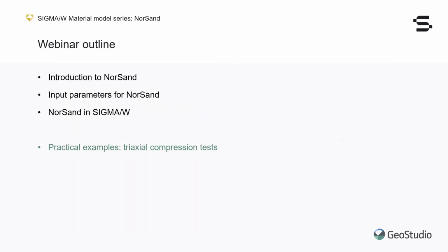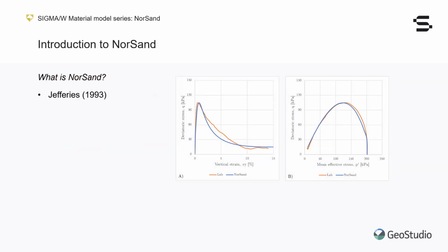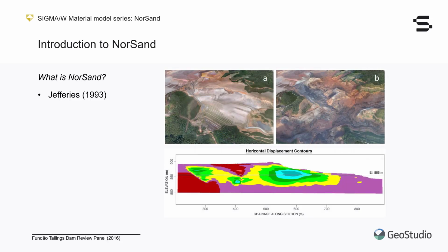Let us start this webinar by reviewing the important basics of NorSand. NorSand is a constitutive model created by Mike Jeffries in 1993, which has been updated and upgraded considerably through the years. It is a soil model specifically designed to correctly simulate sand behavior for a variety of states, from dense and dilatant samples to loose and very contractive ones, such as what we see here, where static liquefaction is simulated by the model. Although NorSand's primary application is geared towards sand behavior modeling, it is also well equipped to deal with other materials, such as silts and tailing materials.